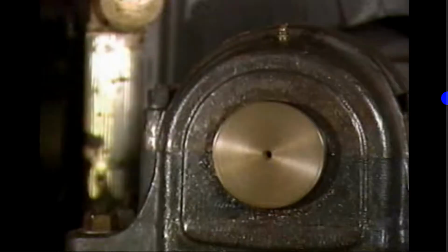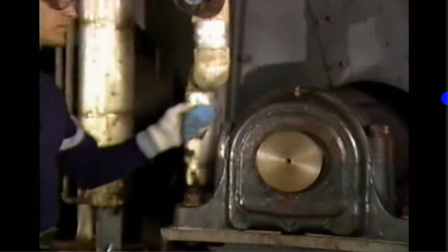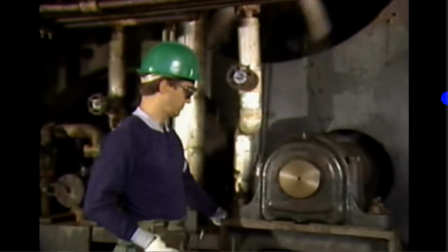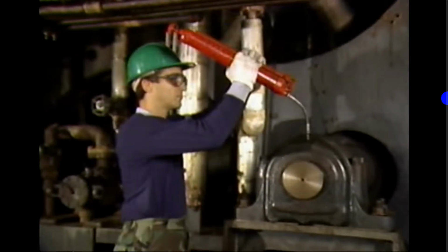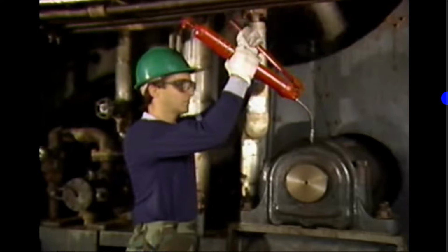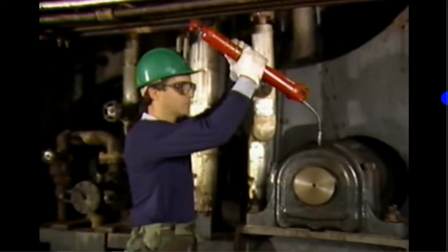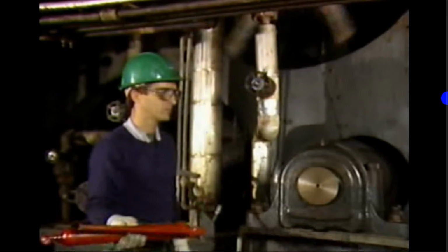If the housing doesn't have a drain plug, the excess grease or old grease leaves the bearing through the shaft seals. In this case, it is very important to add grease slowly to the housing so that the shaft seals are not damaged. A good rule of thumb is to pump the grease gun no more than 2 or 3 times unless specific plant guidelines state otherwise.